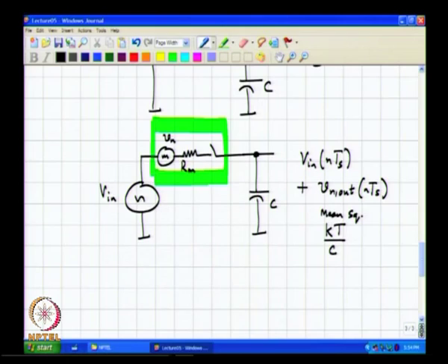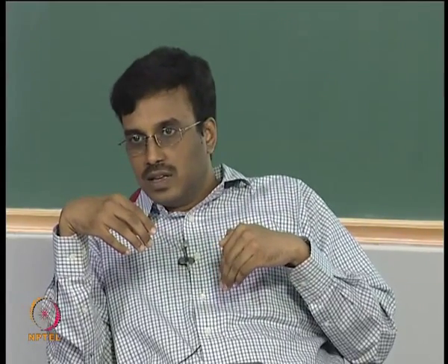So, if I take a general RC network and find the mean square value across the output of some capacitor, if I increase all the resistors by the same factor, it will turn out that if you measure the mean square noise, the increase in the spectral density will be compensated by the decrease in the bandwidth, and you will get the same mean square value. Okay.